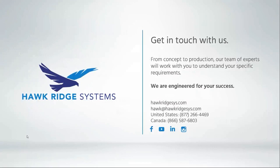I have a question here about AutoCAD drawings. One thing to know about PDM is it doesn't really care what kind of document you put in it. You can put any type of document. What's great about AutoCAD is that through eDrawings, you're going to have previews, and it's also going to recognize your references when you put the files in there. So if you have references within your AutoCAD file, it will recognize that and auto-populate your contains and where used. So yes, definitely AutoCAD drawings in PDM, please.